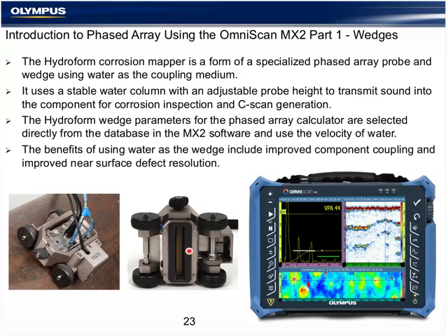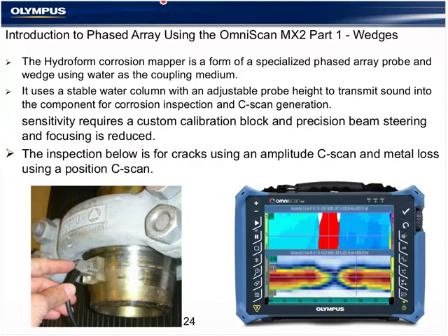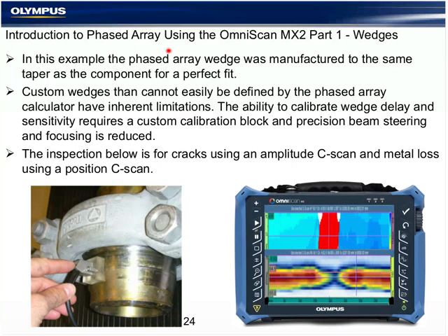And it allows us a feature often used in immersion tanks called a floating gate and echo synchronization on the A-scan, meaning that I can set a gate over the interface signal, and my other positions for backwall 1 and 2 become floating gates. And it gives us a lot of immersion tank functionality in a small portable system.